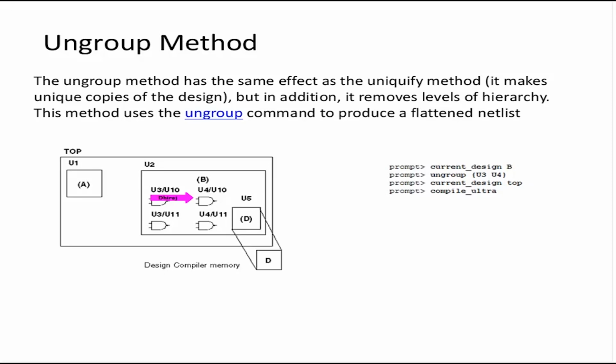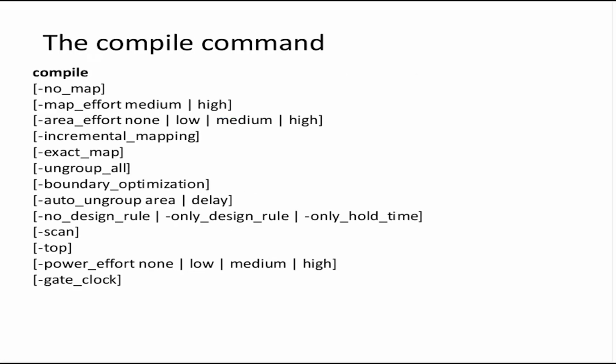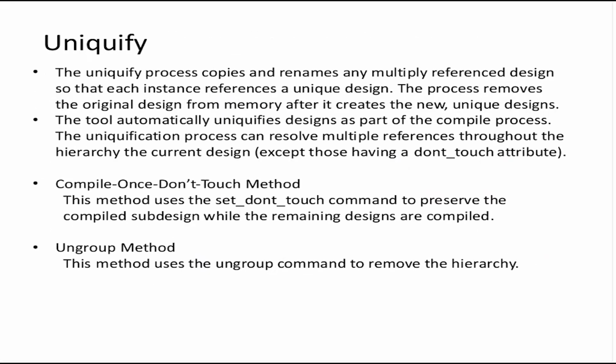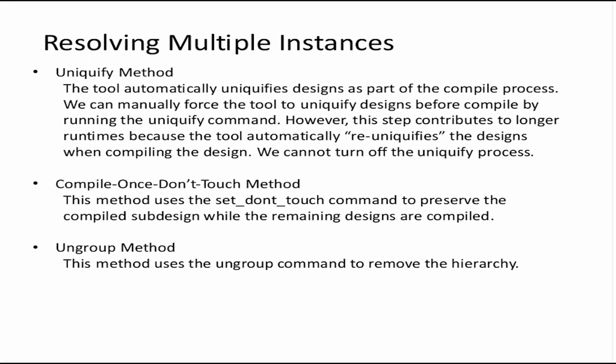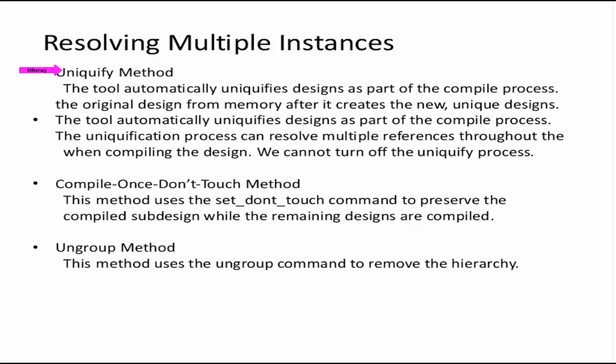So we saw three methods of resolving multiple instances: unify, compile once don't touch, and ungroup. I would again recommend using unify. That is the default. You don't have to specify any separate command. The compile command itself will do it for you.